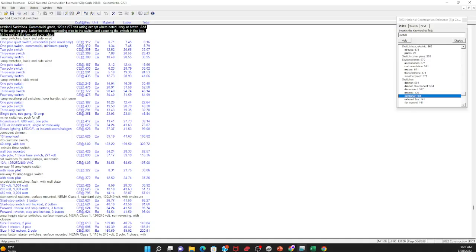And so they give you the industry standard on everything in construction, whether it's a switch, whether it's the conduit, whether it's a wire, and that's the number that we use in the Excel spreadsheet. The number here after the @ sign basically says what portion of a man hour it takes to install one. So the unit is each.